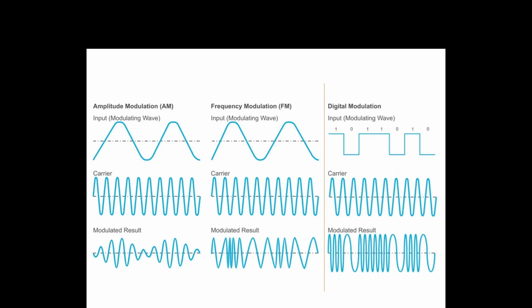This is nothing but frequency shift keying. This is the example for the FSK, frequency shift keying method. A digital input is modulated with the help of an analog carrier, and the frequency of the modulated signal varies with respect to the input digital signal. This method is simply said to be the frequency shift keying method. This is one of the examples of a digital modulation technique.